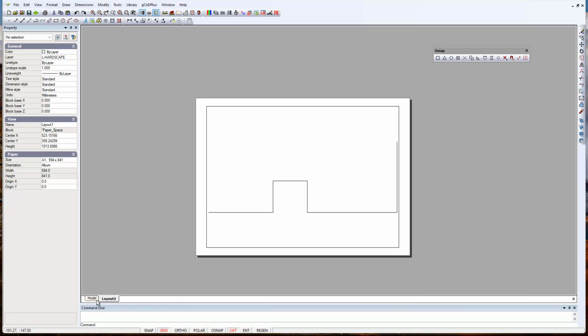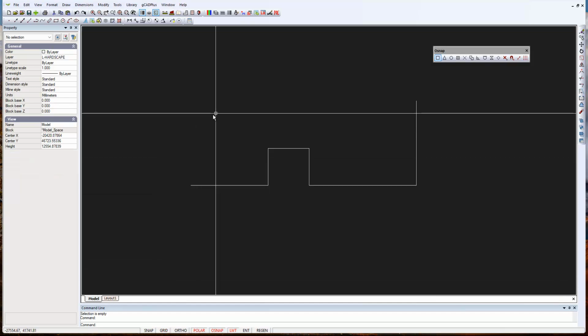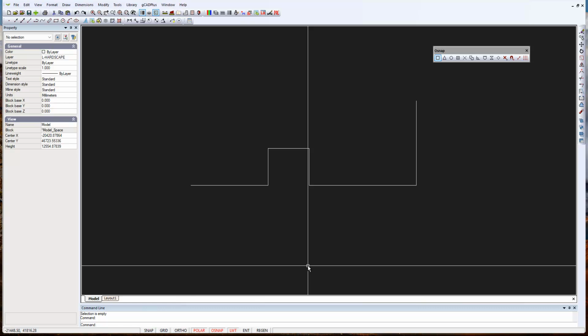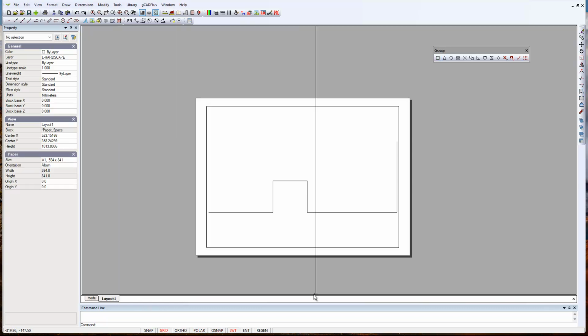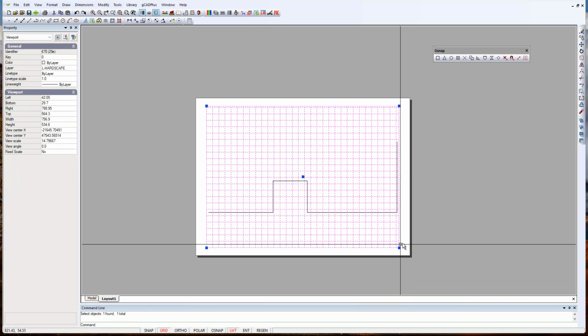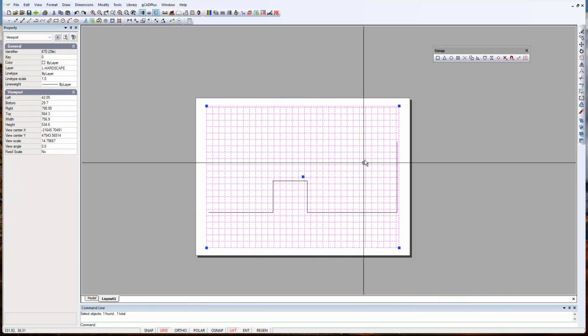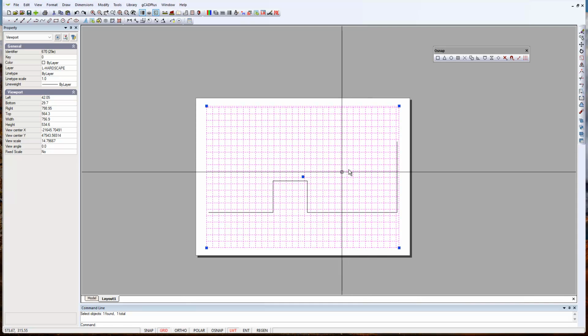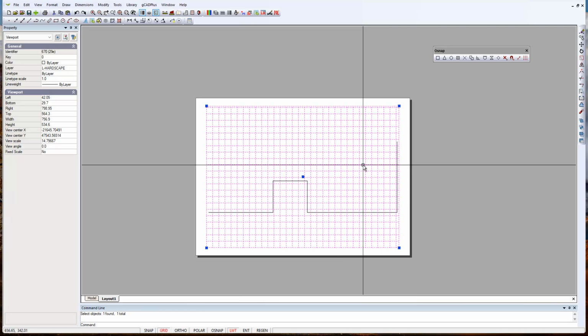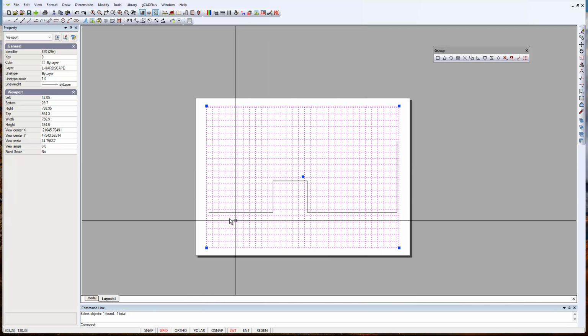So you do 90.9% of your drafting work in model space and only worry about layout space and scale at this point. So we can click, it's gCADPlus has automatically set what's called a floating viewport around that layout, and it's given us a view scale, and I could, let's make it just for the sake of argument, and you'll see what happens.